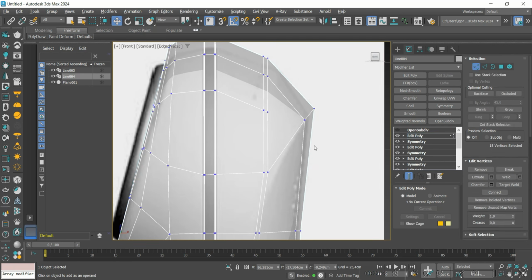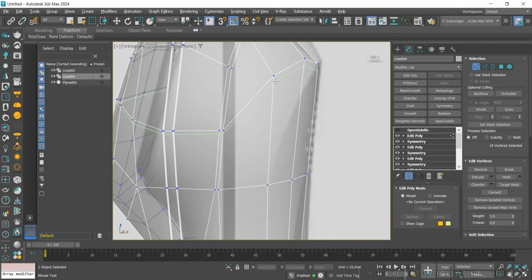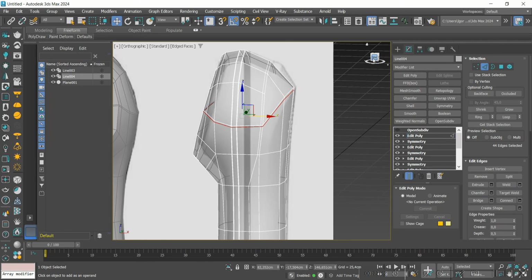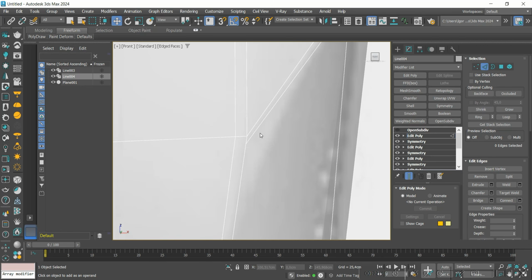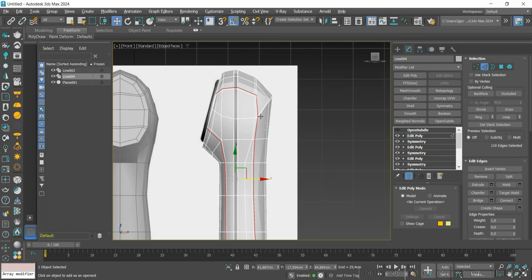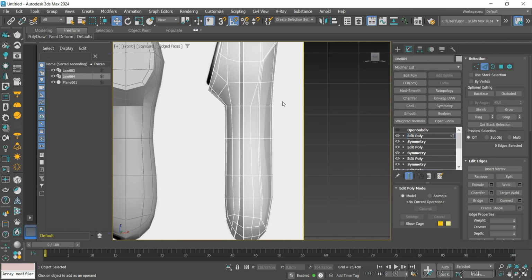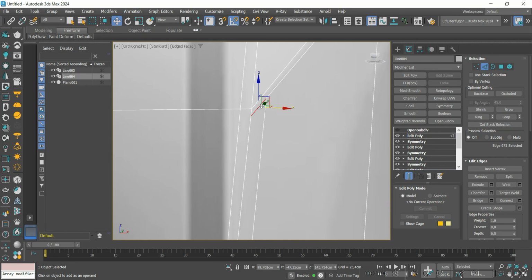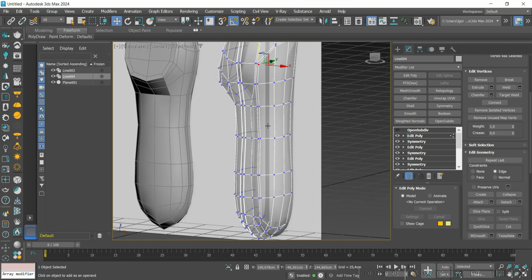To create this detail at the top, let's add a new loop. Let's remove the front part and keep only the lines closing the edge. Now, let's insert a loop in this part and remove these lines from the front part. Once it is done, we adjust the mesh connections so that it's working correctly. Let's do the same for the bottom part.